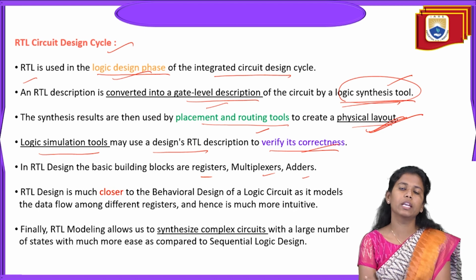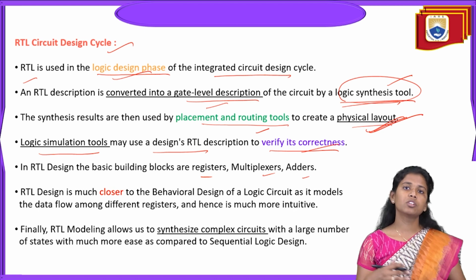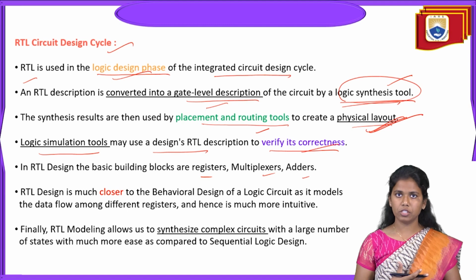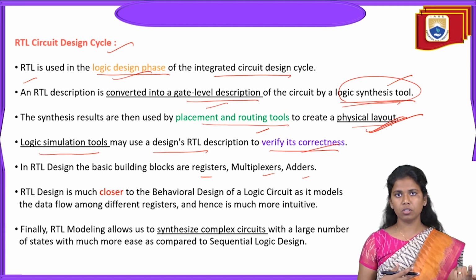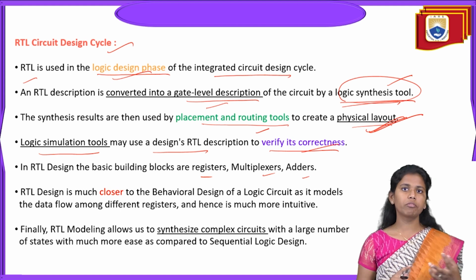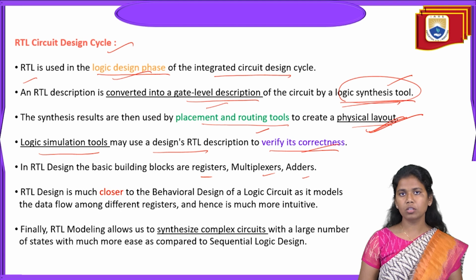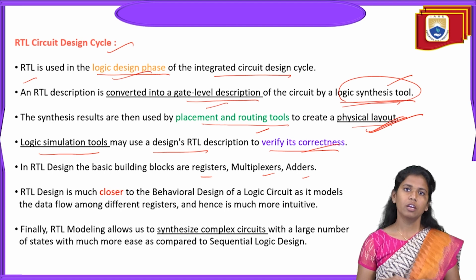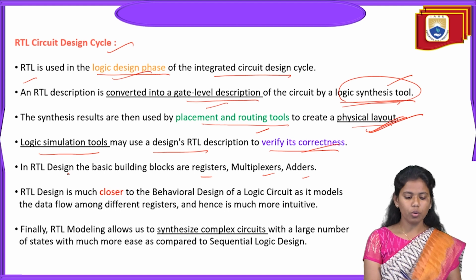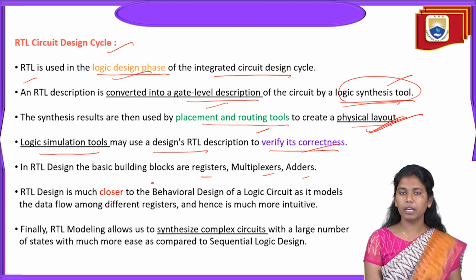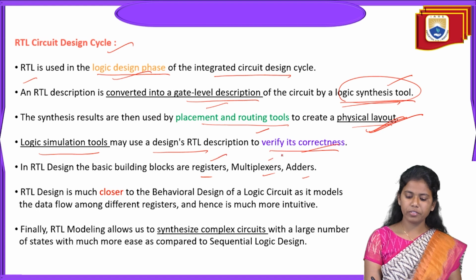So in register transfer level, as we have discussed, the purpose is to create a high-level description, where the RTL can go with the registers or the sequential logic, and also with the combinational logic as well. In the sequential logic, we have discussed that flip-flops, the memory elements, are the major basic building blocks, whereas in the combinational logic circuits, basic logic gates are the basic building blocks, right? So here in the RTL design, the basic building blocks could be either multiplexers, registers and adders.